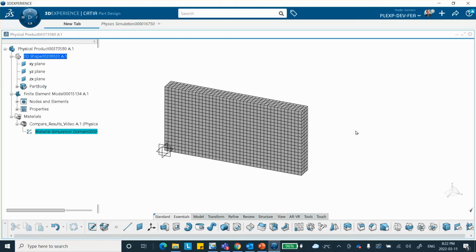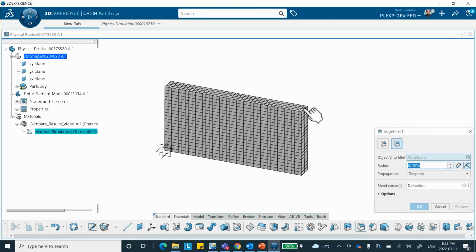As I said, creating an abstraction of the original part is a better way of doing it, but that's what we're going to do. So where is the fillet? Right there. So I want it at that face, at that edge, and the bottom edge, and 1 inch fillet. Preview looks like this, and we say okay.